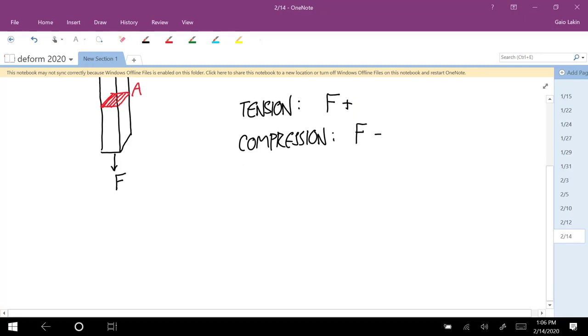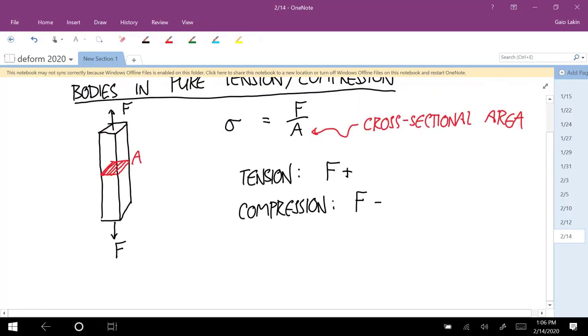And one of the things that's going to be really useful for this is, okay, so look at that picture. It looks like that load is being applied as a point load, right? I mean, that's the way I drew it. But if you really applied, well, first of all, there's no such thing as a point load. Even the sharpest knife blade makes contact over some amount of area. But if you really applied a point force, then if you thought about how this would deform, as you got up close to where that force was applied, you'd be stretching out. It would be sort of bulging out there, you can imagine.